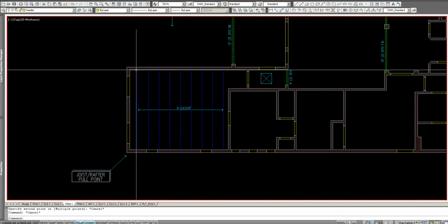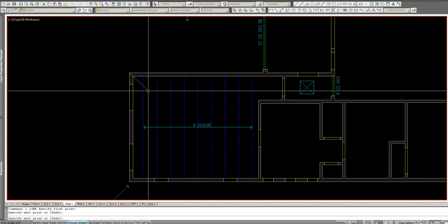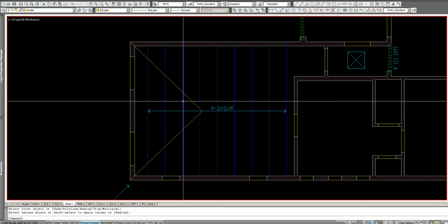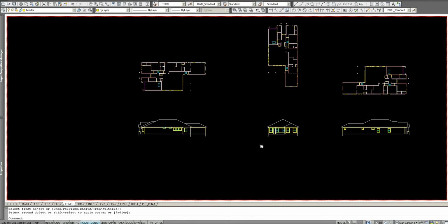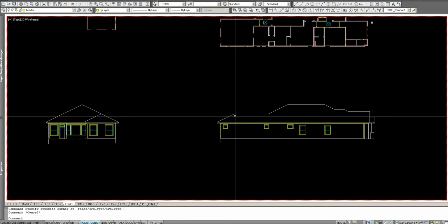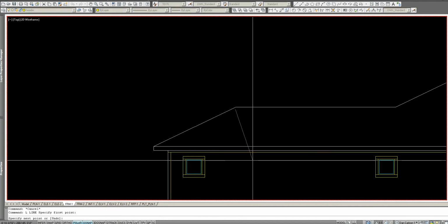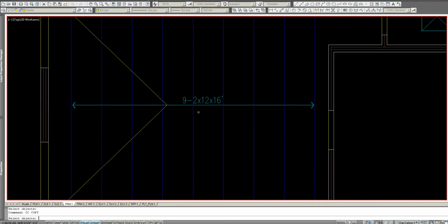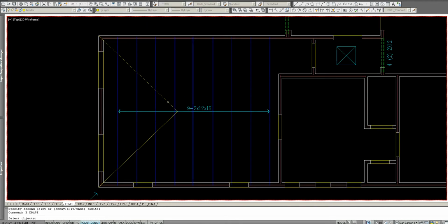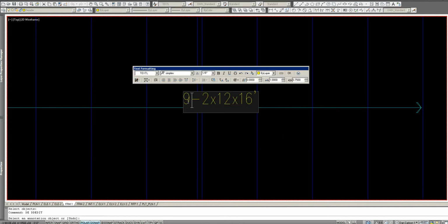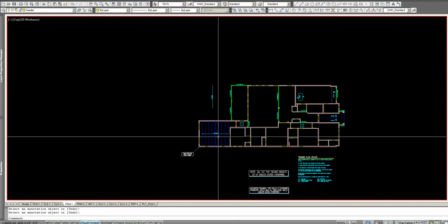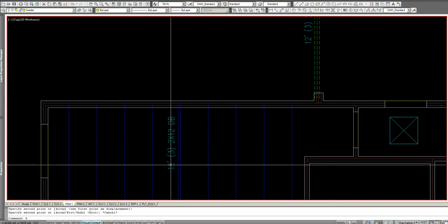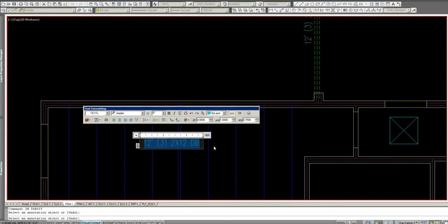Now, incidentally, I also know that there is a roof that comes back here, and we know that it is a hip. There it is right there. Under this point, we're going to need to put a support to help hold that up. So we may as well just come in here right now and double this one and change this to 10. And you can take a little text and call it DBL for double.